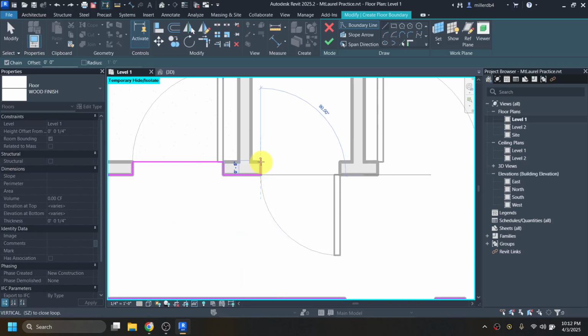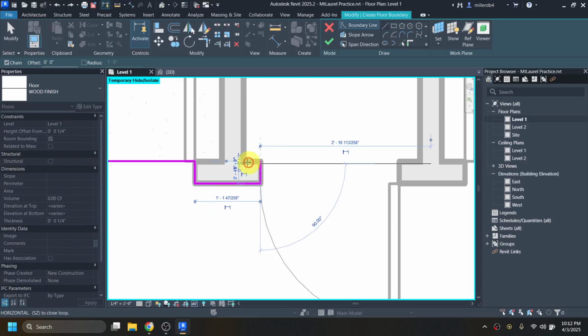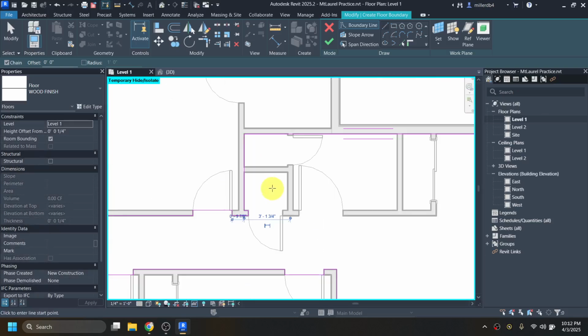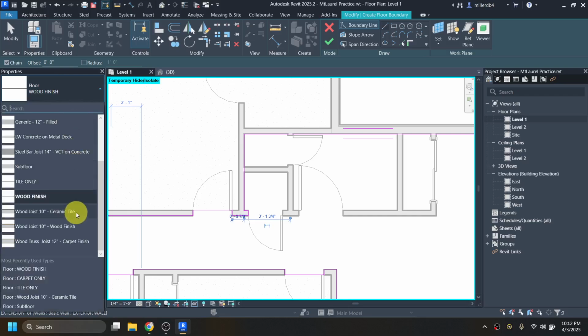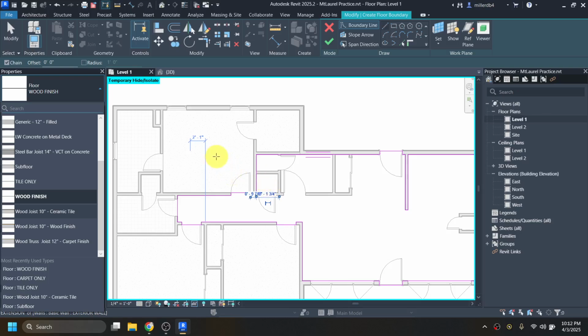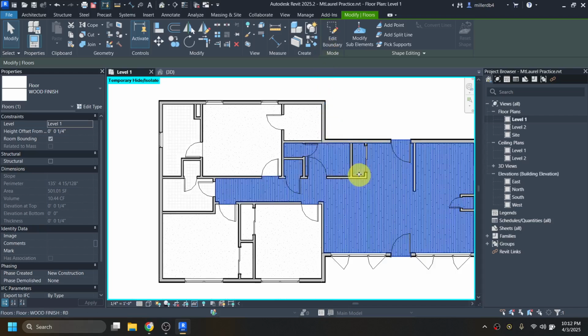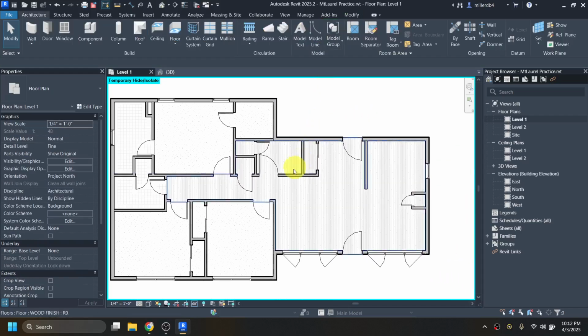And I've also seen plenty of people make their walls, or rather their floors, differently than I do. Really, you could have your whole system built out and then only put a carpeted one where it already has your joist, your subfloor, and such, all as one, like how these ones are pre-built out. But I just prefer my method. It makes more sense to me, because otherwise you have these weird gaps hanging out underneath walls. So I'm going to hit the green check. I've got my wood floor in there.